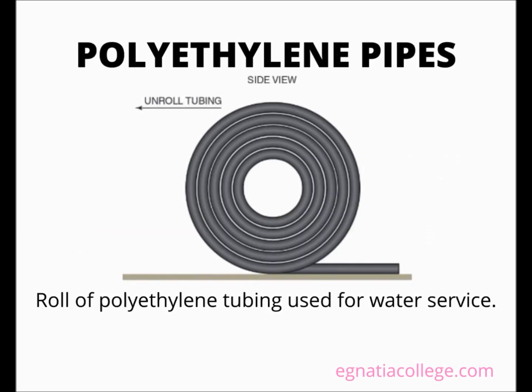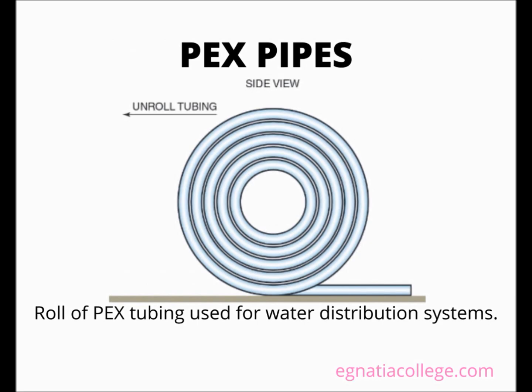Polyethylene pipe. Polyethylene (PE) tubing is used for water service installations, but codes do not allow for its installation on the interior of a residential building. PE tubing is black in color and is typically sold in 100 feet rolls. It is often used in well pump installations because of its long lengths and durability in cold conditions. It is joined together with specially designed barbed connections and stainless steel hose clamps, so that it can be pressurized immediately after a connection is complete.